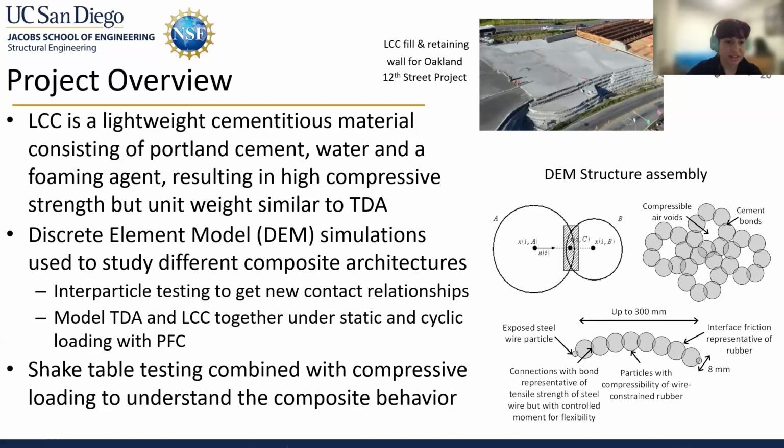This NSF project will be utilizing discrete element modeling, or DEM simulations, used to study different composite architectures like the ones mentioned earlier. Interparticle testing will be conducted to get new contact relationships between the LCC and TDA particles, and models of TDA and LCC together will be used under static and cyclic loading within PFC. Then a shake table testing combined with compressive loading to understand the composite behavior will occur. Next slide, please.